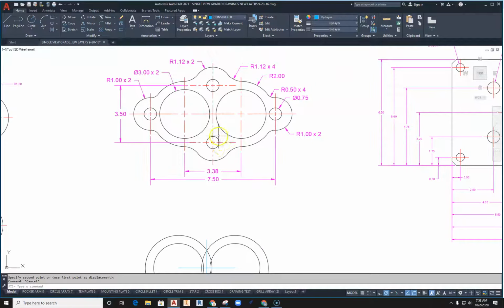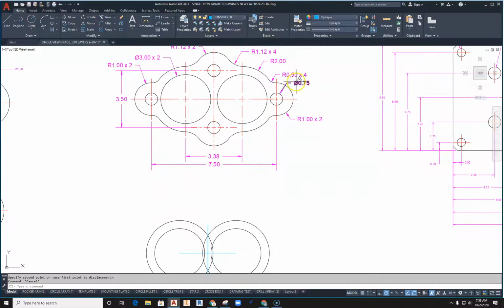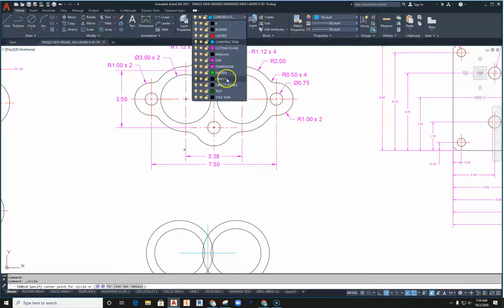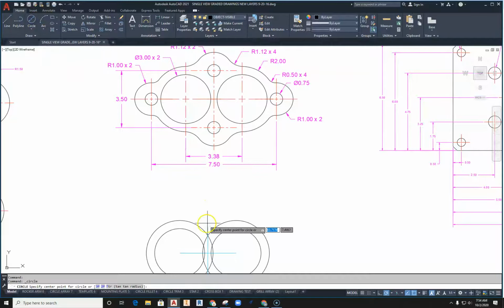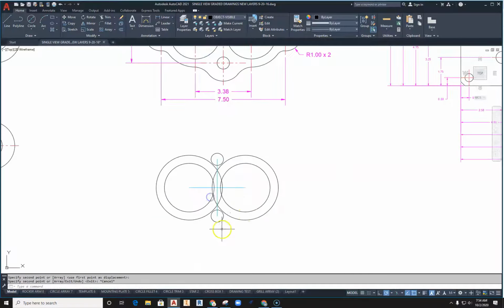So at that point, I can go ahead and create this circle. Now, there's no dimensions on these, but these are all set off of this dimension right here. So this is 0.75. So we got a 0.75 here and throughout the rest. So we'll go ahead and this is diameter also. So we'll pull this down. First, I need to change this to my Object Viz layer. Then we'll go diameter, and we'll click and pull, 0.75. And since I know I'm going to need more of them, I can just go ahead and copy it. Sometimes the copy tool is a little faster, dropping it there.